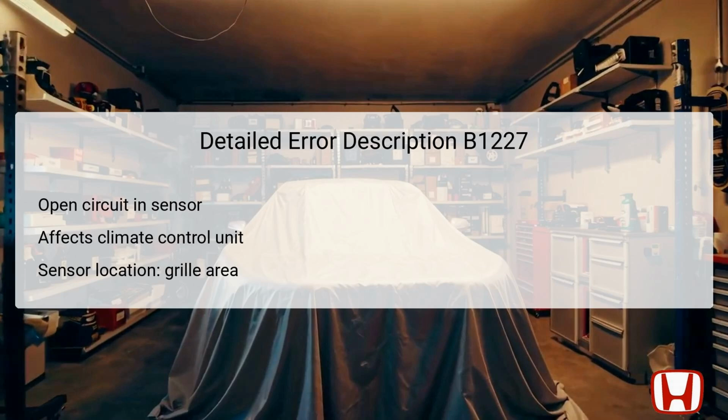DTC B1227 is triggered when there's an open circuit in the outside air temperature sensor wiring, or the sensor itself. This component is essential for the climate control system as it helps the vehicle manage heating and air conditioning efficiently. Typically found near the front grille, this sensor detects the ambient air temperature and sends this information to the climate control unit.